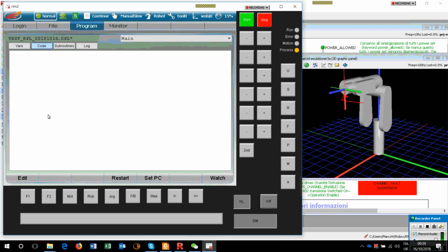So we must teach the robot to start the motion, so for example to a 0 position, which is always the same. Then we say, okay, go here, go down, take this, go up. Don't touch the computer, so go up. Go down, leave this. Then go up again. End of the cycle. We do this to the customer, we have finished. Okay? Half a day we made the installation to the customer, job is done. This is very easy. So, what we do today is properly this.